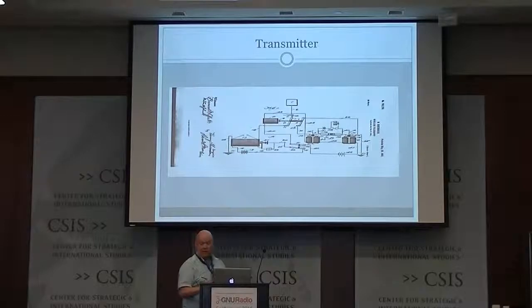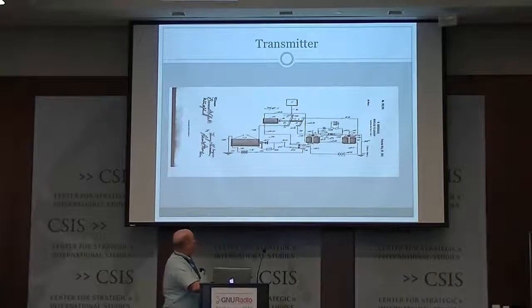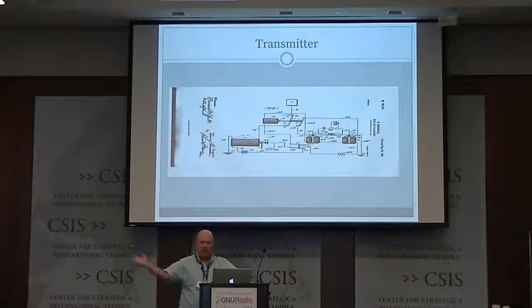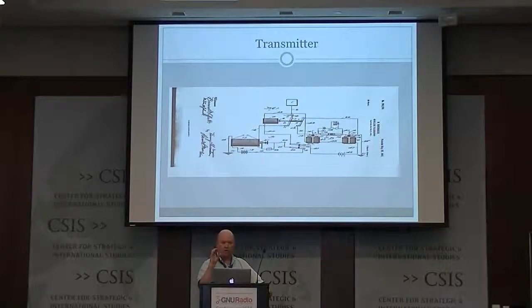This is the patent on the spark gap transmitter. That is a picture from the spark gap. Basically, you had a thing that generated a whole lot of ugly sounding noise. It was just horrendous. And you could see the sparks as the wheel would go by and generate these massive sparks. And they didn't want to transmit over every single band there was with this system, so they would put a tuned circuit after the spark generator. And the tuned circuit would focus the RF coming out of it a little bit.